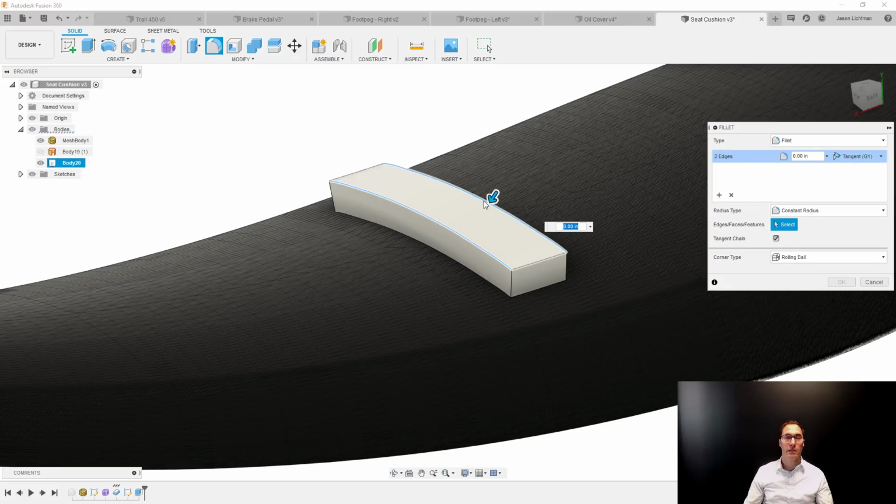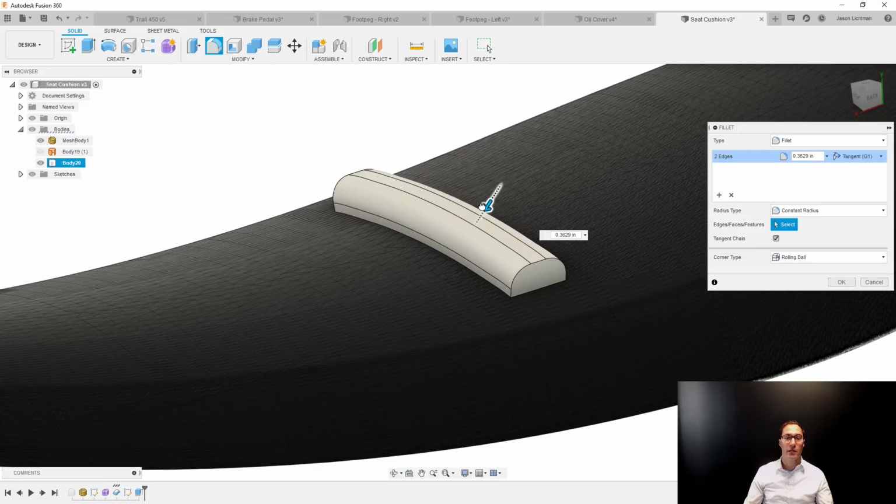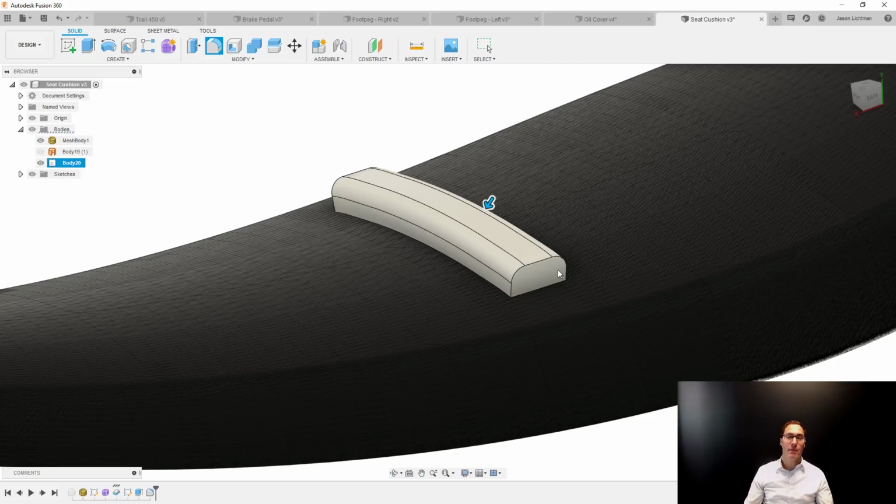So maybe in this case, it's going to be filleting this thing like crazy. Maybe we'll add 1/4 inch. Something like that. Maybe I extend this, maybe I don't. You guys get the idea here. I'm able to take a T-spline surface, make it match a mesh very quickly and easily, and then be able to use traditional modeling techniques in the B-rep or parametric solid modeling or surface modeling environment to be able to make whatever I want. And this is going to be a perfect fit.